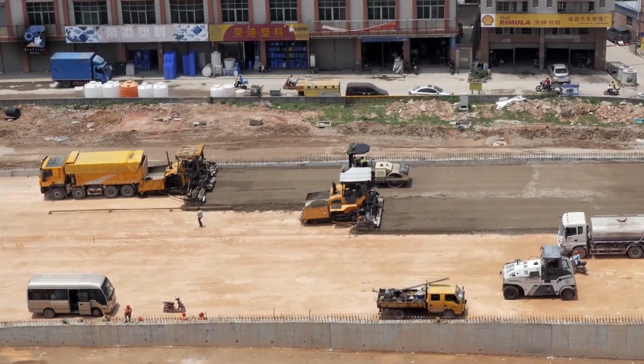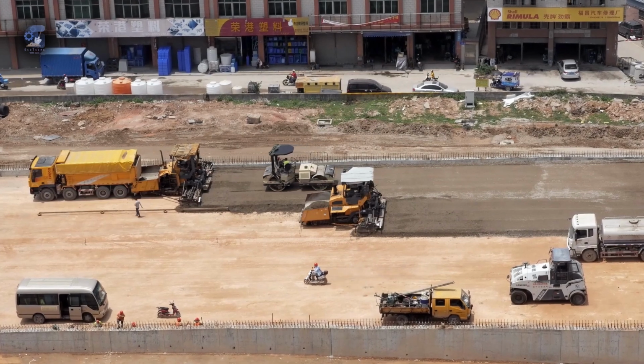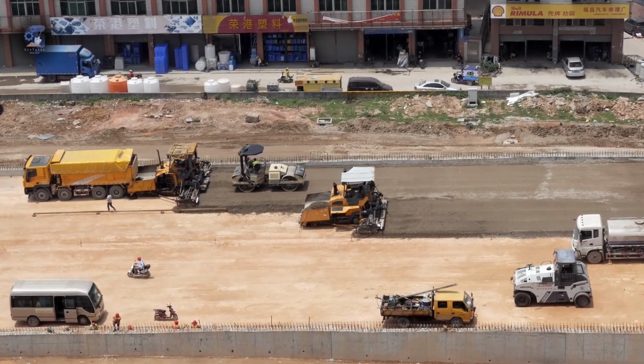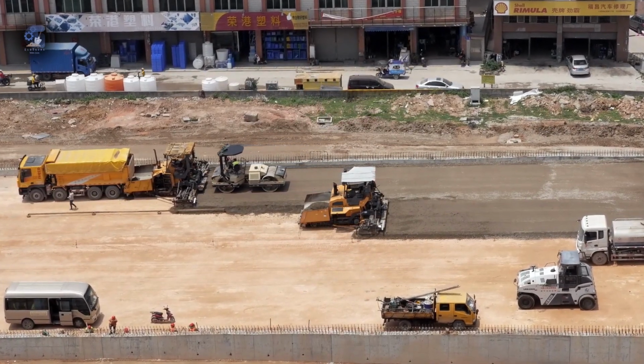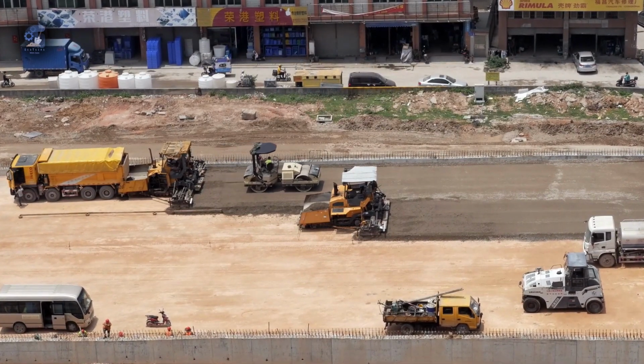The subgrade, which is the top surface of the roadbed upon which the pavement structure and the shoulders are constructed, provides a working platform for the heavy construction machinery and equipment. Furthermore, it should have enough bearing capacity to support the pavement without undue deflections that would impact the pavement's performance.